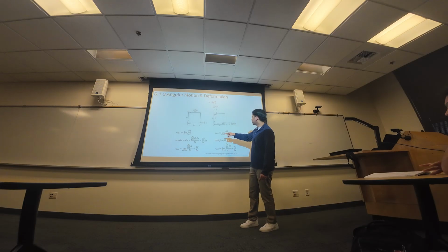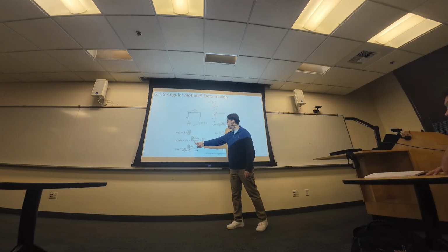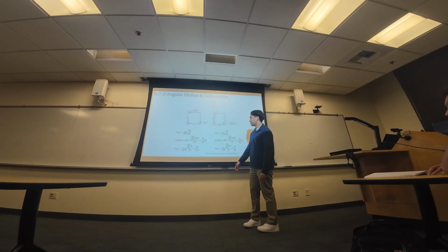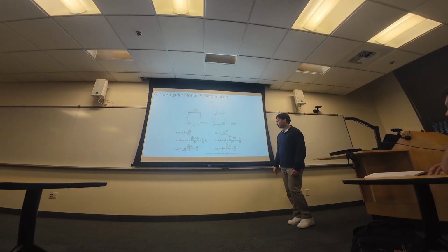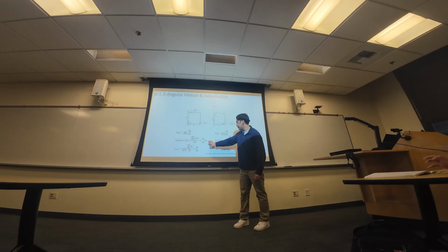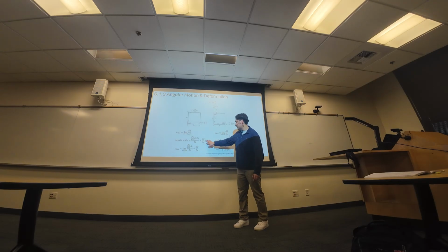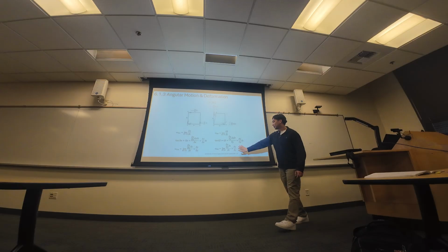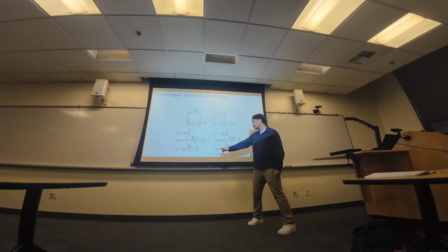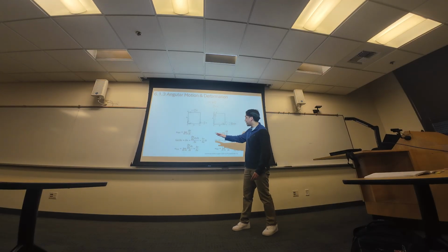So for your alpha, you take this divided by this, and you get angle delta alpha. You keep working that out with algebra and you get this equation here. Then if you take the limit in this next step, the time cancels out. So then you get just this value here for omega, which is angular velocity.